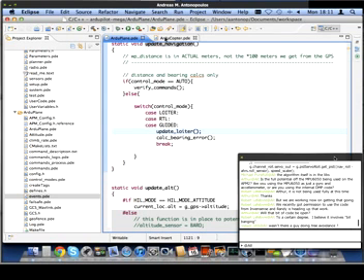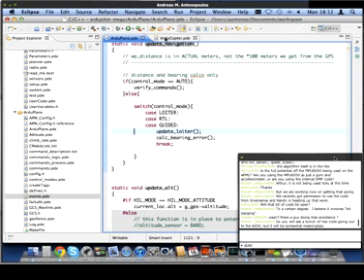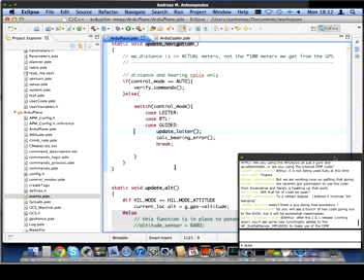It may be that the recent DCM updates, which haven't actually been released yet but are in the current Git master tree, have improved our pitch estimation code considerably. Combined with the better smoothing that we now have on the sonar analog to digital converter, much more accurate smoothing is available because of the interrupt-driven A to D code. It may be that the sonar is now worth a look again on ArduPlane, but Doug hasn't had time to rerun his experiments.